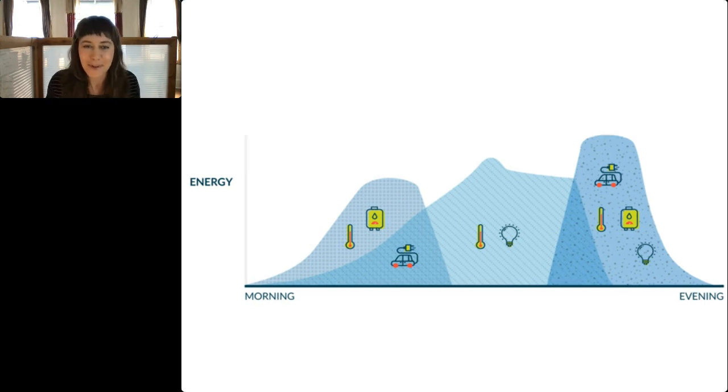Now, I somehow messed up on my slide, and I did have a solar load shape here, but what you would see is that this solar load shape really peaks in the middle of the day, let's say. We could add a wind load shape too, but for most grids, you're talking about still wind here, solar here, and then in the evening, anything that falls outside of those curves is really primarily being powered by gas turbines or coal-fired generation.